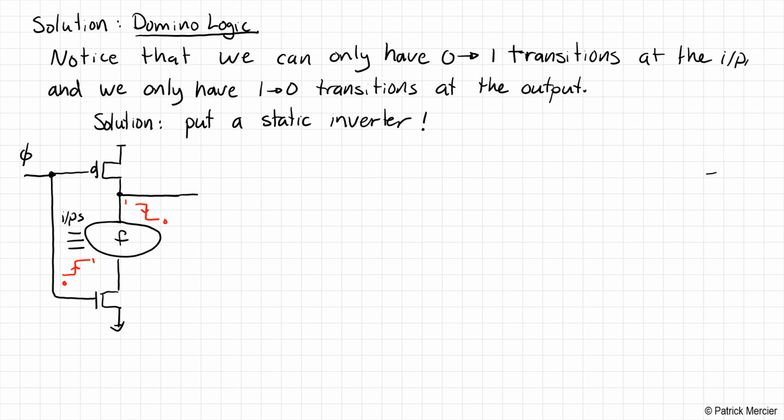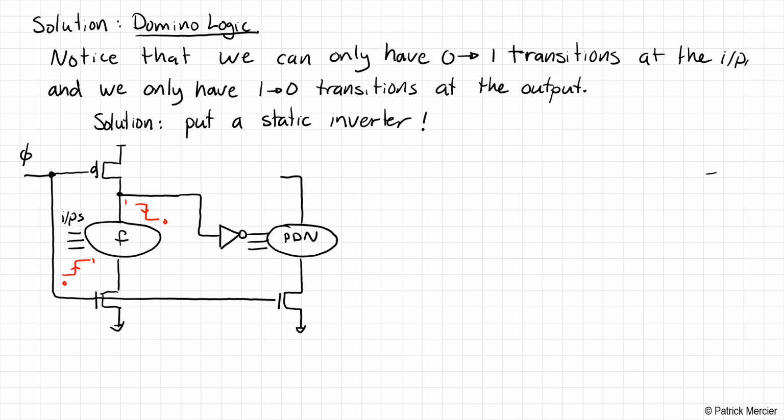So the idea here is we take a normal static CMOS inverter and use this as the inputs to some other pull-down network in a dynamic logic circuit that is the same overall structure as the previous stage here. And again, when I draw the input going through here, that doesn't mean it's connecting to the bulk. I'm ignoring the bulk in this drawing.